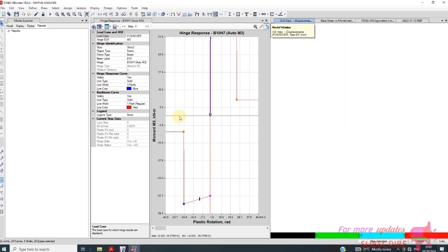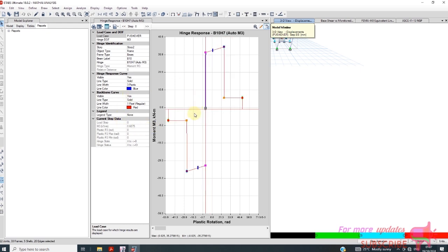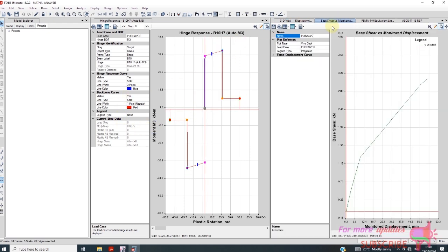NSP converts multiple degree of freedom models, utilizing pushover analysis to determine capacity curves, typically in the form of base shear versus displacement at the roof. The use of ground spectrum in some form with this capacity curve can estimate the maximum global displacement.